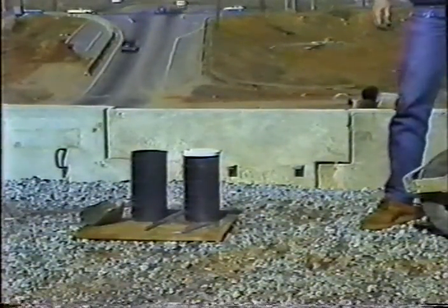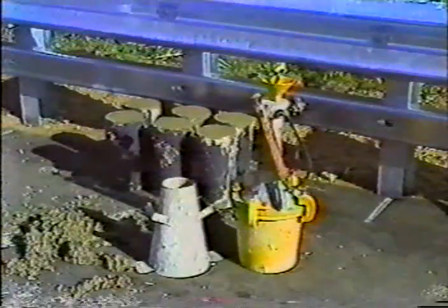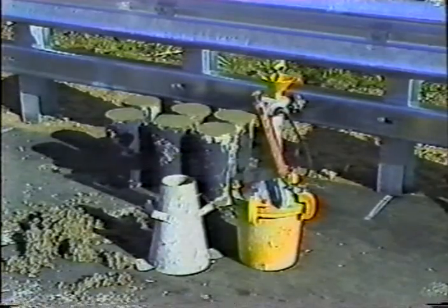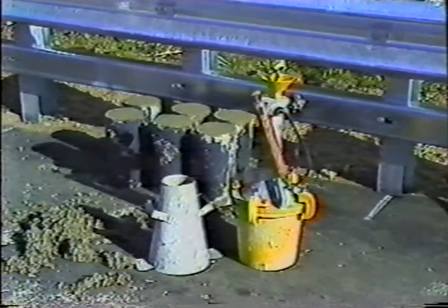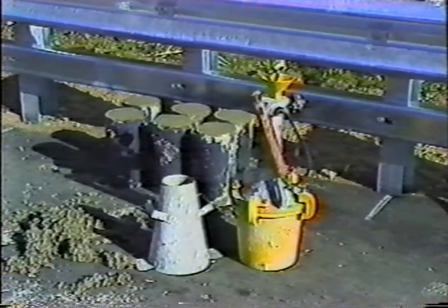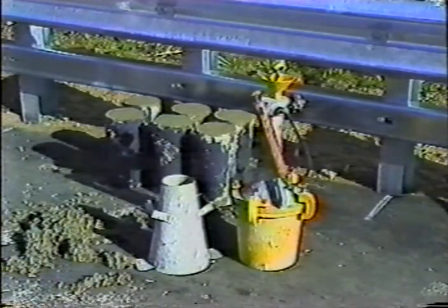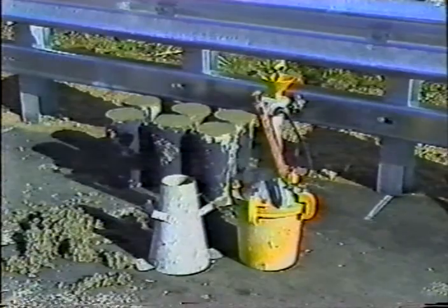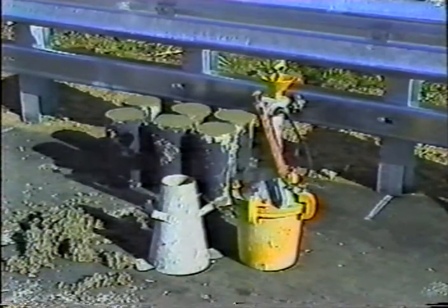Cylinder curing is a critical part of the testing. Try to keep all cylinders undisturbed for the first 24 hours, buried with dirt within 2 inches of the tops, covered with the caps supplied with the cylinders. But that's not all, because there are variations, which your instructor will discuss after the program.